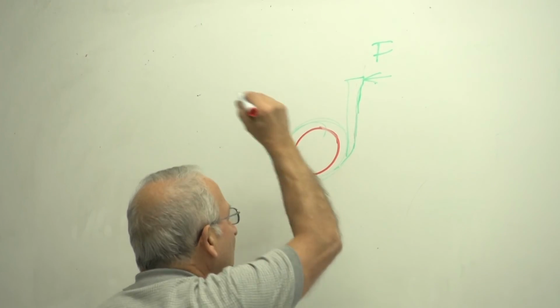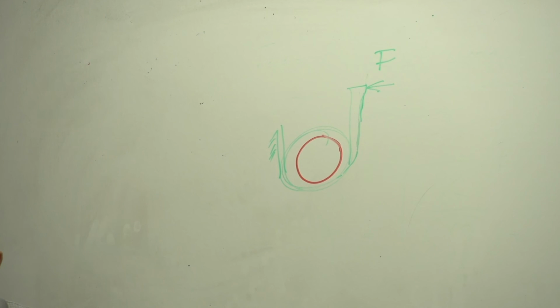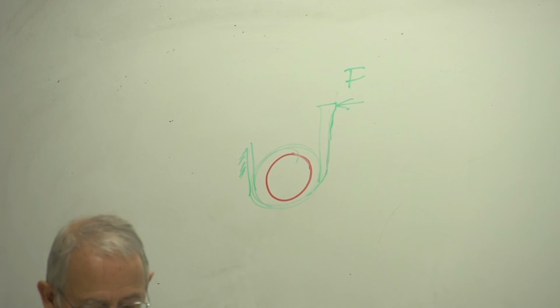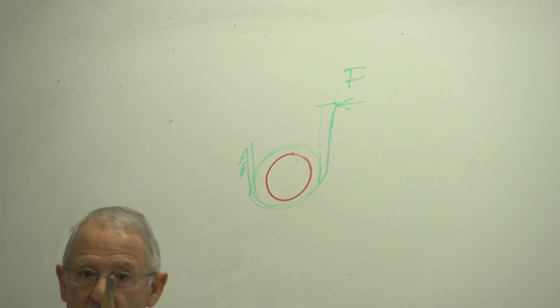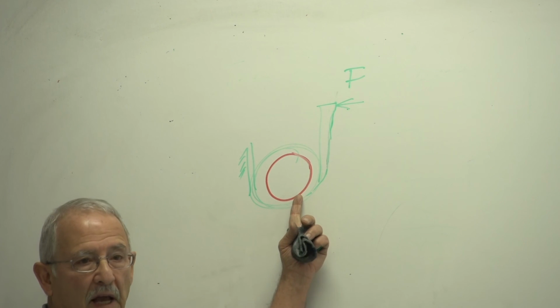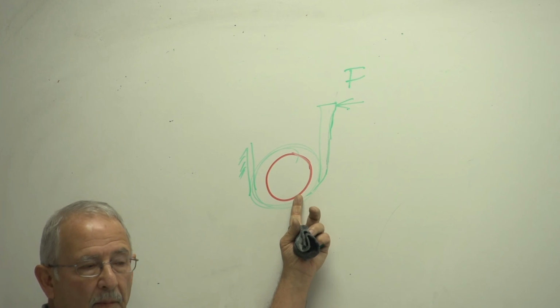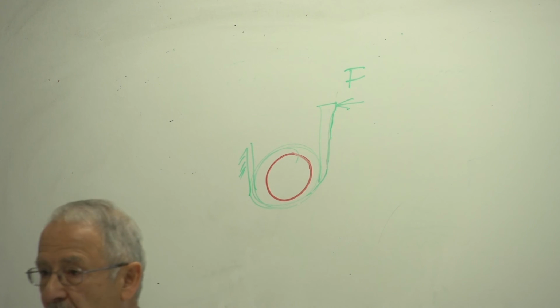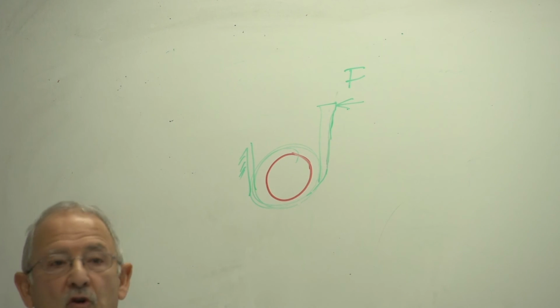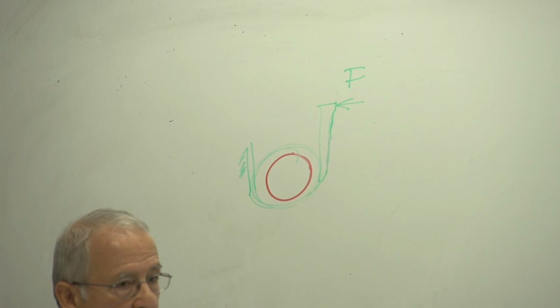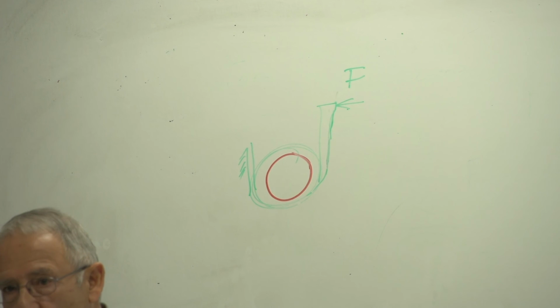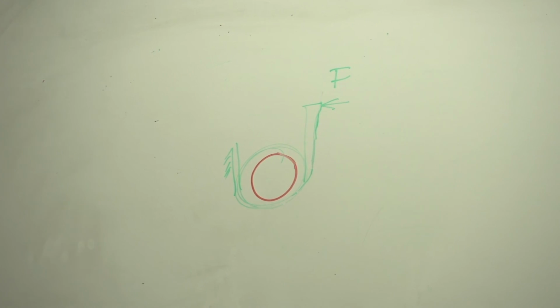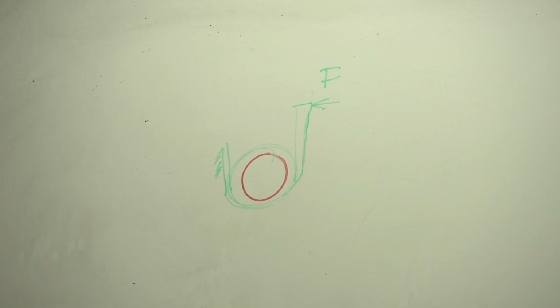you've got to make sure that the internal diameter, the inner diameter of the spring, does not become so small that it actually touches the mandrel. In order to do that, you must be able to find the internal diameter of the spring after load from the internal diameter of the spring before load, and the load, of course, or the number of coils. There is an equation that will give you that, and that is this equation.